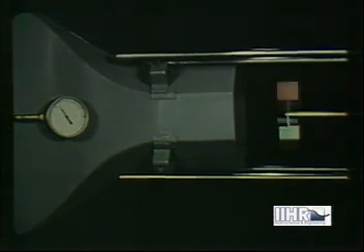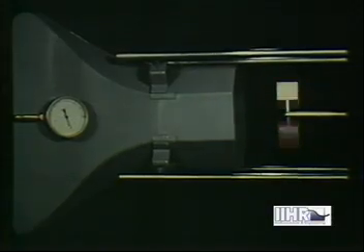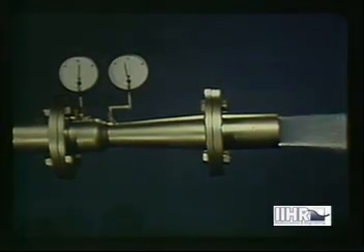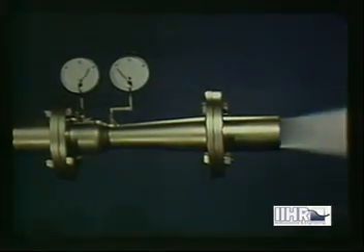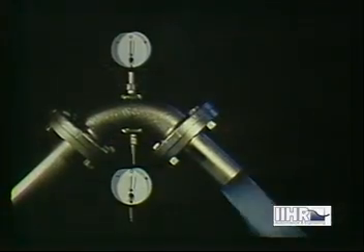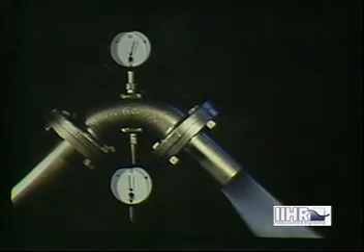Instead of the acceleration of flow around a body, the acceleration of flow through a conduit transition, for example, the contraction preceding the test section of an air or water tunnel, can be used in the same manner to produce a pressure change that varies in a known way with a velocity change. A similar condition forms the basis of what is known as a Venturi meter. In fact, any boundary form that produces a change in the direction or the magnitude of the velocity, even a pipe elbow, can be used to measure the velocity or rate of flow.